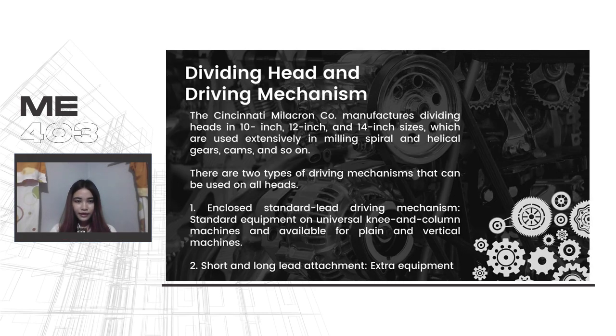We also have the dividing head and driving mechanism. With this, the Cincinnati Milacron Company, an American machine tool builder, manufactures dividing heads in 10-inch, 12-inch, and 14-inch sizes, which are used extensively in milling spiral and helical gears, cams, and so on.